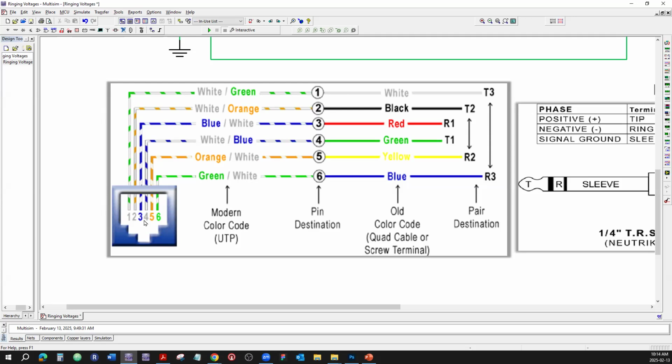Usually, those are being used to connect 1 pair, even though the jack's capability is to connect more than 1 pair. And where does that 1 pair, or pair number 1, tip and ring, live? It lives in the 2 middle prongs. That's where we look for the signal for POTS, plain old telephone service. You can see that here. Tip and ring 1. That's the first pair if there was only 1 telephone line connected to it.